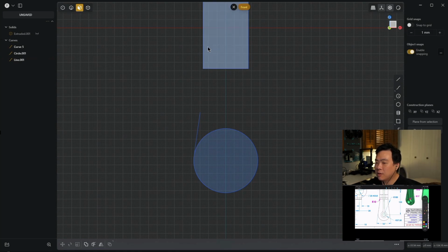But first of all, we need to draw a line that we need to intersect with that runs vertically. So using the line tool again, I'm going to click on this corner over here, making sure that the degree is 90. And then the length of it doesn't really matter right now. I'm just going to left click and then right click to confirm.